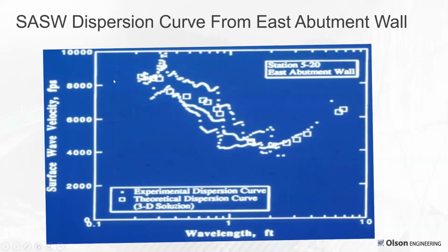So what that means is there was sound shotcrete over freeze-thaw cracked original concrete over sound deeper concrete, which was good news.